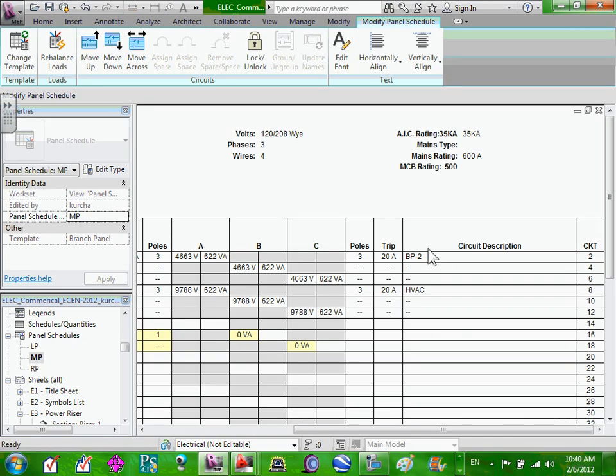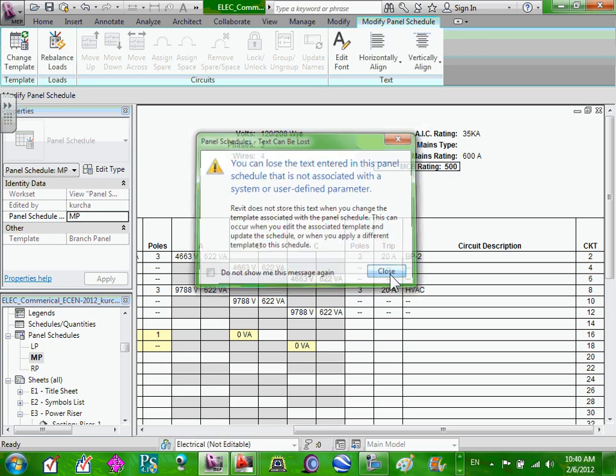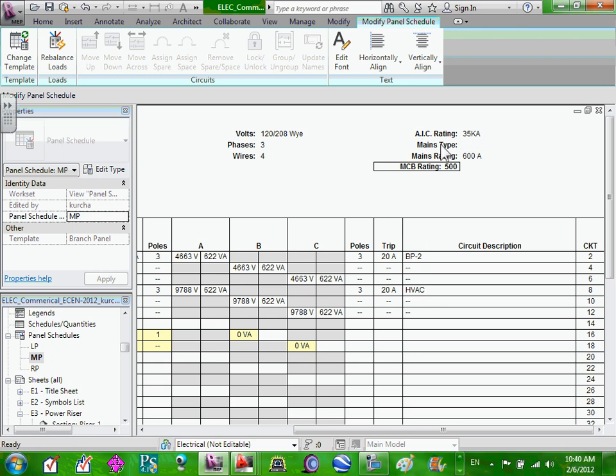So if you double click on the schedule, it should get you, here you go. See where I was editing, actually, it's a value that you can input. I deleted it. Okay. You can input this value as a parameter. You don't have to edit it there. If you input it as a parameter, it will come also as a parameter. Which is the best? Put them as a parameter. Okay, guys, Chad, that's a good start for the schedules. Okay, so 3 schedules: lighting schedule, mechanical schedule, lighting and main panel, as well as the receptacle panel.